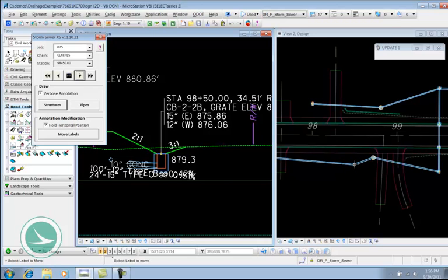What's going on here is it's showing those two pipes as a linear and not just as a circle in the catch basin. The program is written to look at the offsets from the center line at each end of that pipe. And if those offsets are the same or nearly the same, I can't remember the exact tolerance number, it's probably in the PDF documentation, it'll show it just as a circle.